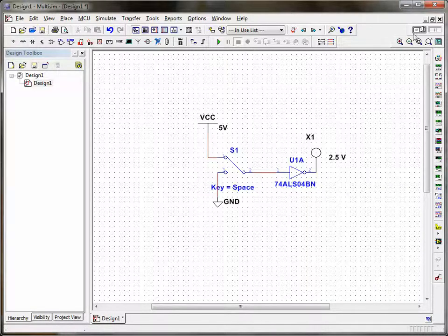You can also turn the switch on here and the circuit will run. Notice the probe is not lit up. Why? Well, we've got VCC 5 volts high coming into the switch, going into the input of the inverter gate, and the output is going to be not in, right? So not high is low, so the probe, or it's like an LED, is off.